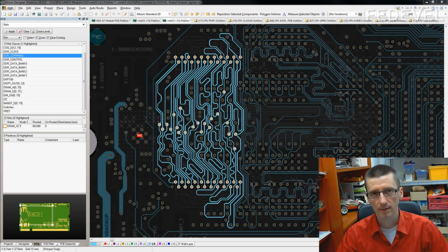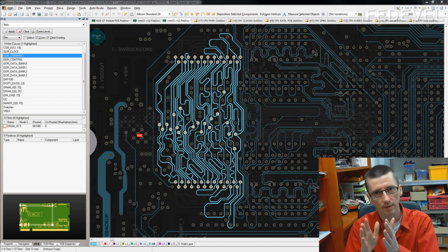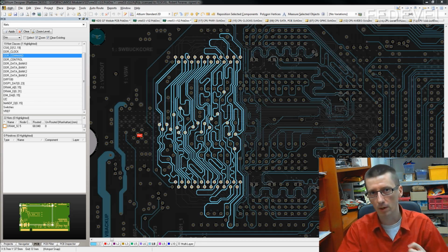For high-speed design, it's very important that all the tracks have exactly the same properties. If you put some of the signals on one layer, some of the signals on different layers, and do them a different way, the properties of this environment may be different. For example, tracks on the top or bottom layer are in a completely different environment than in the middle of the PCB.